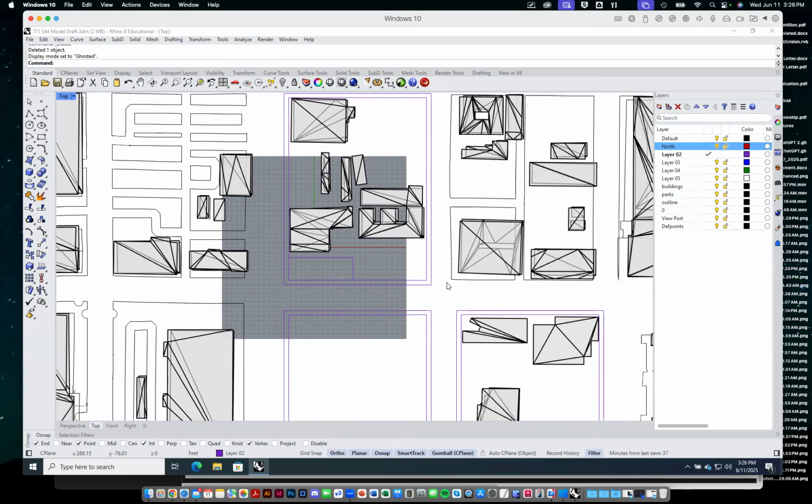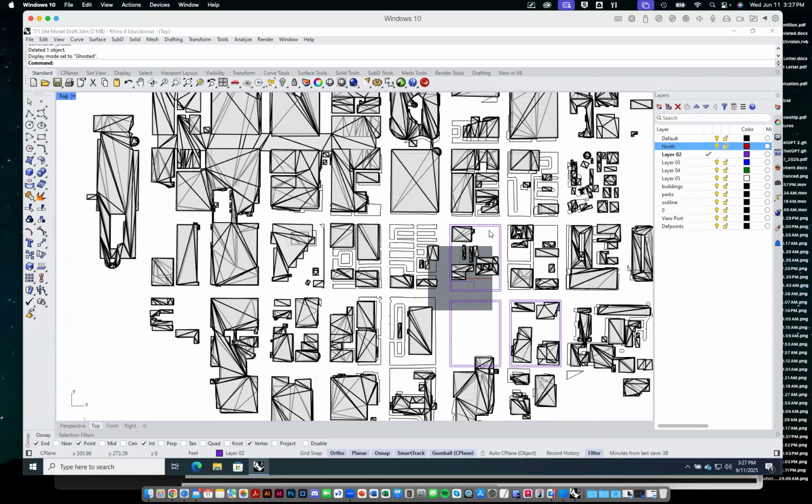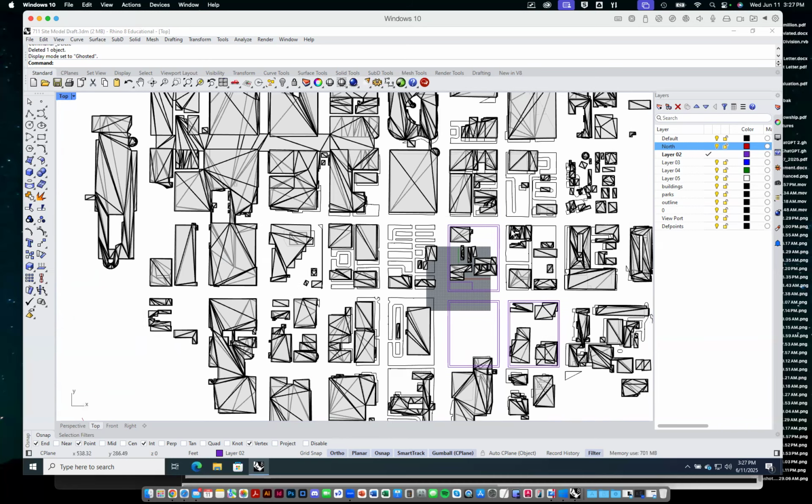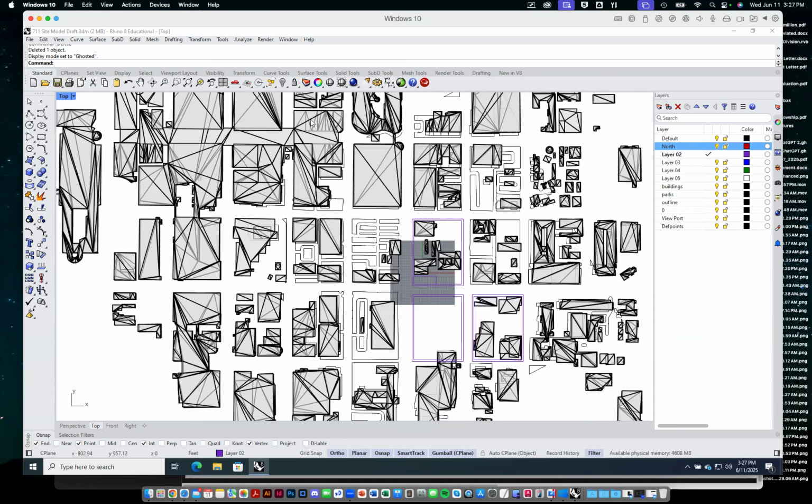Then when we have the actual block information, we can fill that in. It's a closed planar curve. We can fill it in with a planar surface. Then we can extrude it down 6 inches, and then we could just make a surface underneath that's 6 inches below that for the roadway. Right? But here's the key: fix the blocks a little bit for the blocks around, delete all the stuff you don't need, right?